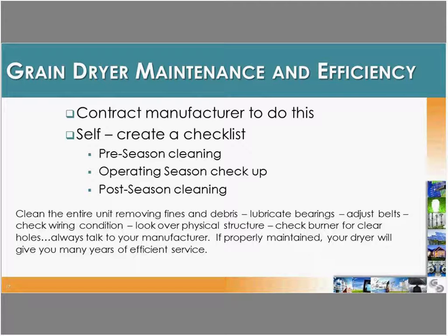So coming back into just the maintenance and keeping your dryer running at optimal performance, again, with that checking of the wiring condition, a lot of the insects, bugs, and mice tend to like to live in there and chew, so you just want to make sure that's all good to go, no loose wires hanging anywhere. The physical structure of the bin, a lot of snow and fines cause that rusting. So you just want to do a walk around, make sure the physical structure is in good condition.